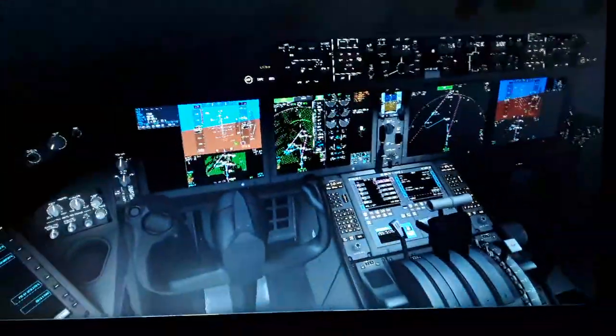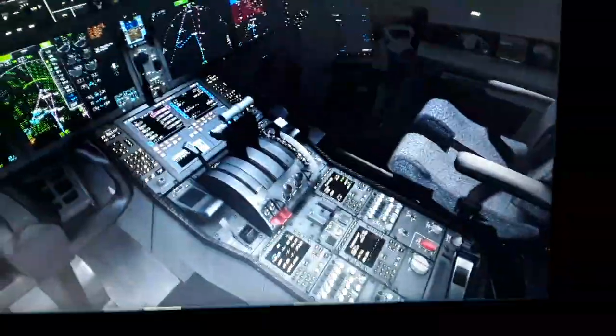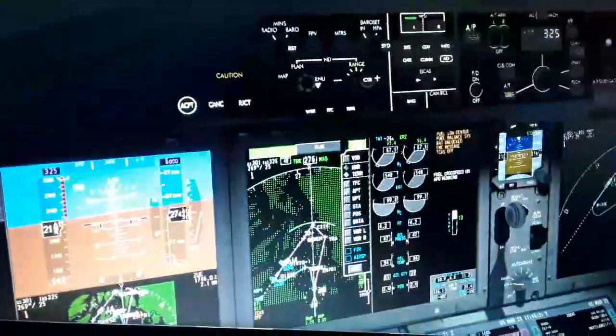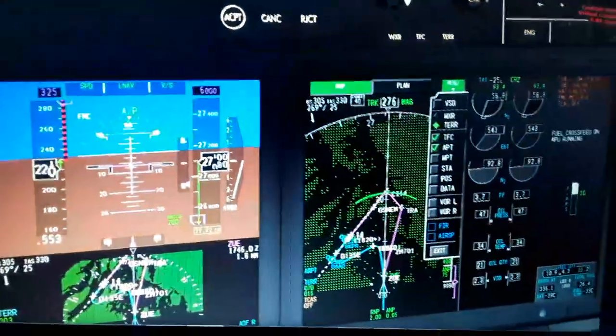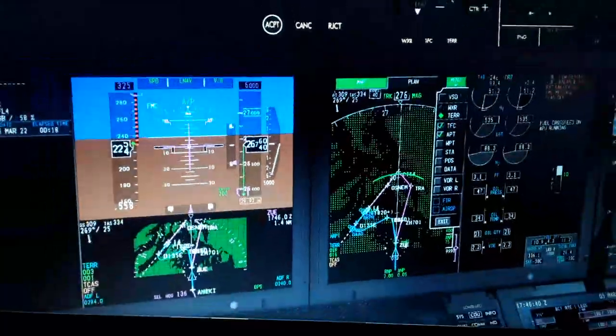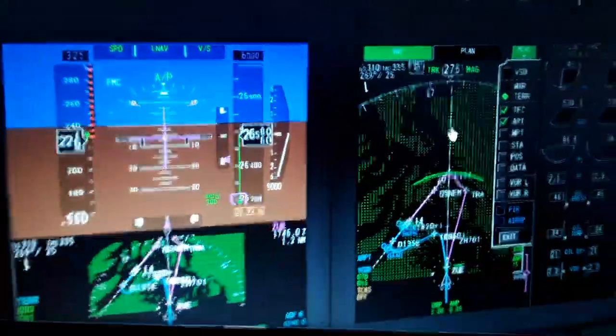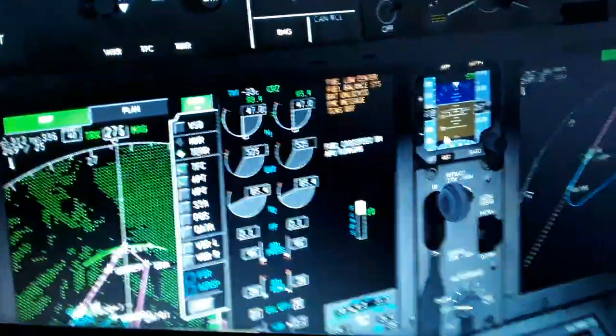So this will give us a higher airspeed. We need to use also the speed brakes, and the thrust will go moderate into a lower setting as we descend. You can see the rate of descent here. We have idle thrust also.